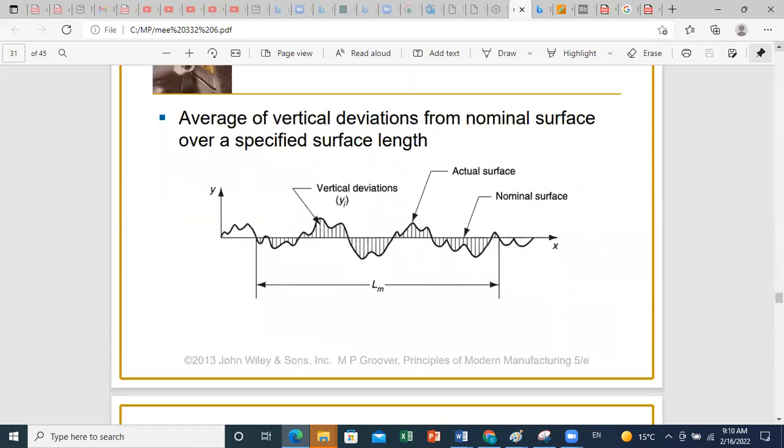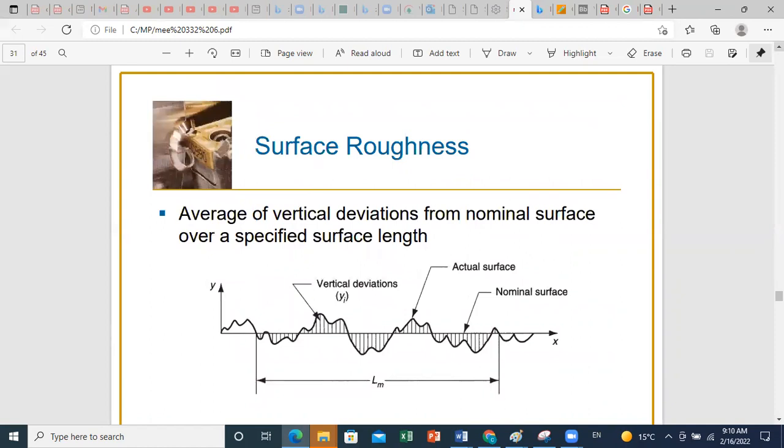So first, in order to measure surface roughness, we have here an example. Let's say we need to have a flat surface, for example, and we want to test after manufacturing it how close it is to the surface desired. We can then measure the deviations in the upper and lower parts. So we'll take the absolute values of deviations, okay?